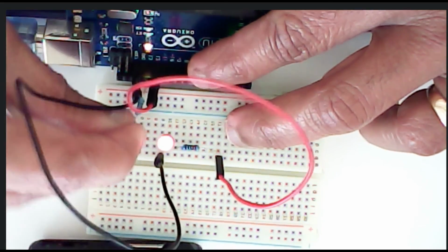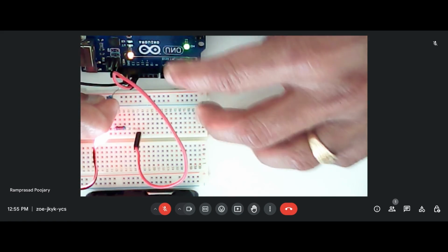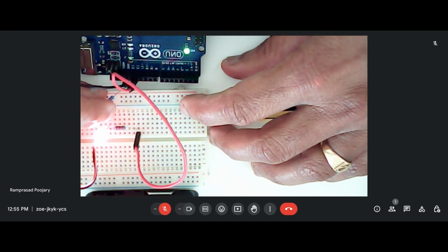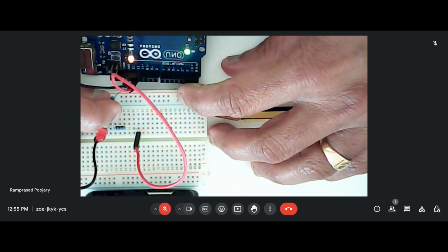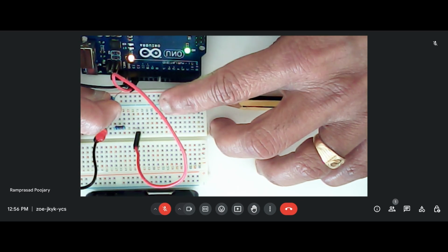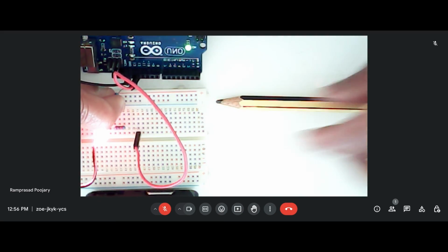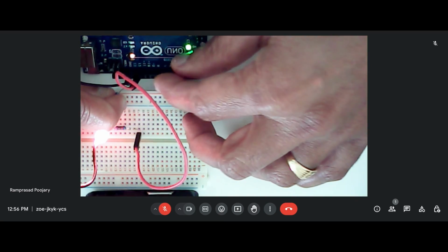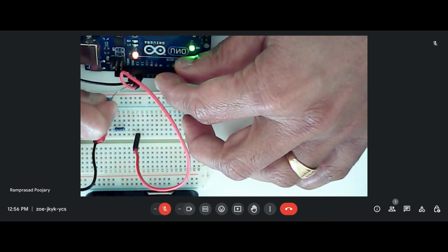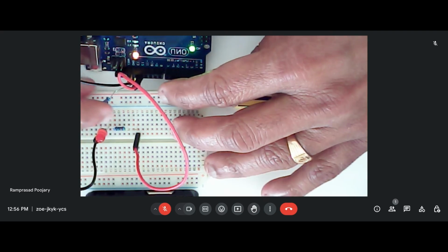to the ground terminal. And as you can see, the pin number 13, I have connected to the ground terminal, the cathode is at ground. This is a 10 kilo ohm resistor. So when a high value resistance is connected to the ground, that means I am connecting pin number 13 to low level. So the LED turns off. The second way is you can modify the Arduino sketch. You can include additional code for turning off the LED at pin number 13.